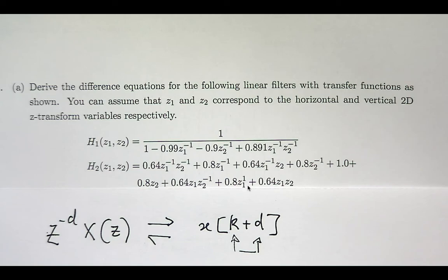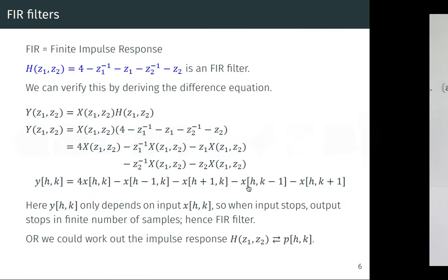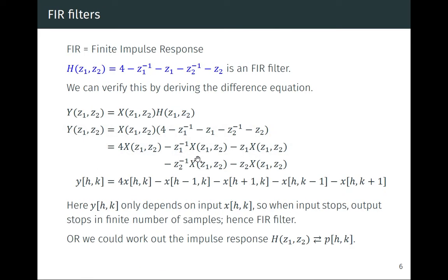Something that you can do back at home. But basically, this is the key for you to be able to recover what the x would be. So coming back to that, once I have all these offsets, I just do the inverse z transform, and I get back to this difference equation. Okay? So that's for the FIR.